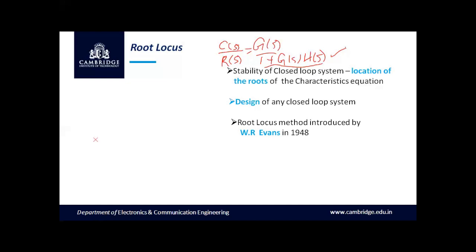In the previous lecture, while we were discussing the second order system, with respect to the parameter zeta, that is nothing but the damping ratio, we have discussed different cases. When zeta is equal to 0, it leads to undamped. When zeta equals 1, we call it a critically damped condition. When zeta is between 0 and 1, we call it underdamped condition.